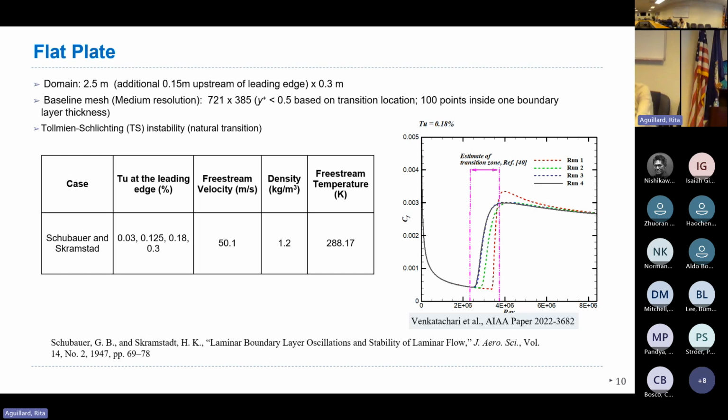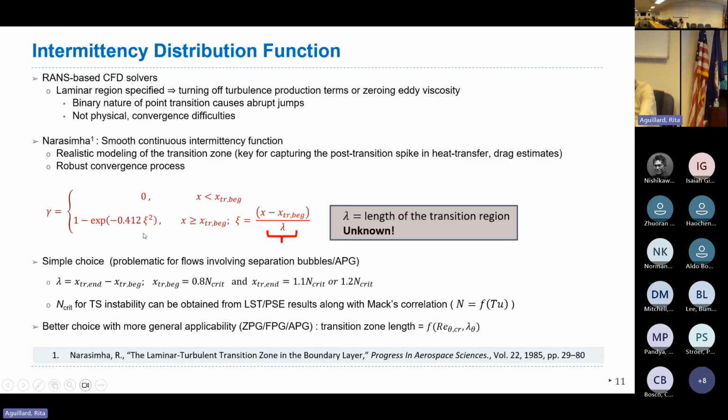So now Ethan, based on different data sets, is trying to fit essentially the same function through that, but he's optimizing some additional coefficients so that you would get that peak, because that's very important. Currently the length is 1, the peak is another one, but in subsonic, we don't have much data for that. I think most people use the experiment by Tom Horvath. Yeah, the tunnel experiments. There are a lot of papers from China using those experiments to calibrate the models. So he is trying to optimize the transition zone length and possibly get the peak as well. So yeah, he's looking at that.